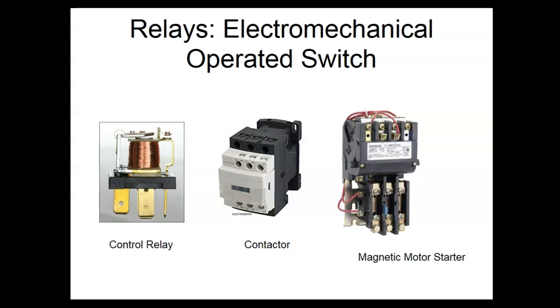The problem with motors is they require a lot of current when you start them. We call that starting current. So when we set up a circuit breaker or a fuse, we have to size the circuit breaker to allow the motor to start. It's like your car. You're at a standstill, and the light turns green. Well, you have to push the gas down further to get the car in motion, to get it started up, and then you let up the gas, and of course you start shifting gears.